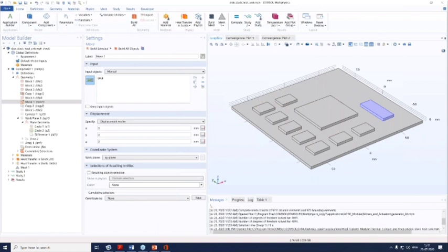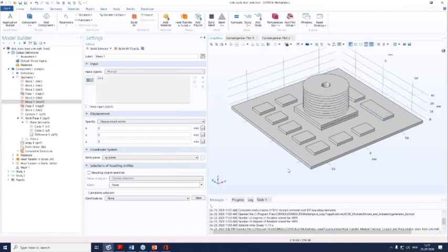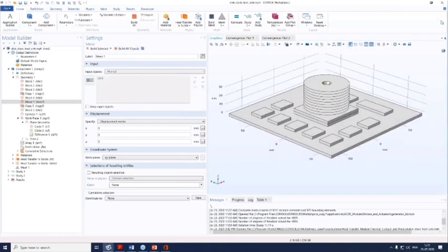How to keep a part of the model hidden in 3D? If you want to hide a certain part, right? For example, I am just building this entire geometry, and hopefully you can see my screen. So here in this case, if you want to hide some parts, you just need to go to this click and hide option. You can see the click and hide option itself, which is given over here. The little eye symbol, which has a cross on it. So first of all, you will need to activate that. Once you activate that, you need to go to this select object button.